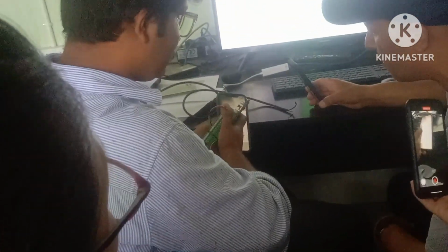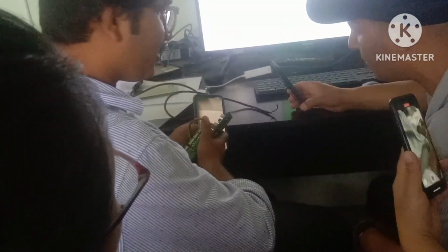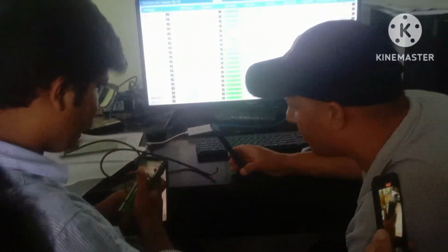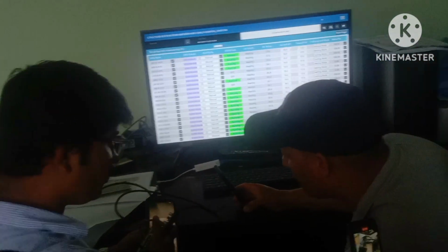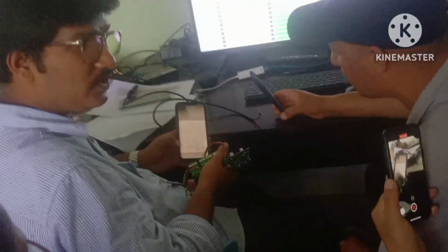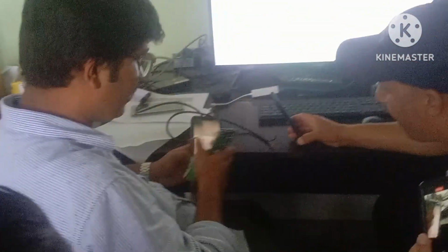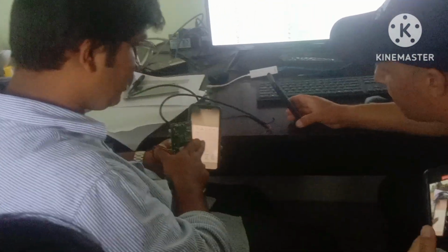Then coming back to this, this is a spare DO, an extra DO given. From here we are going to get an auto manual feedback. We have that selector switch in the AHU, yes, auto and manual, that will be connected here. AHU on feedback, which we are getting.